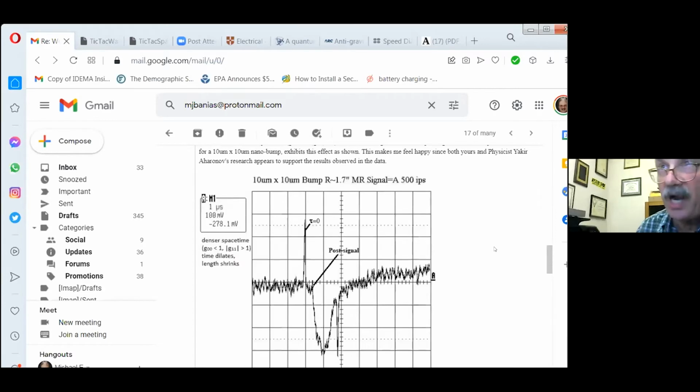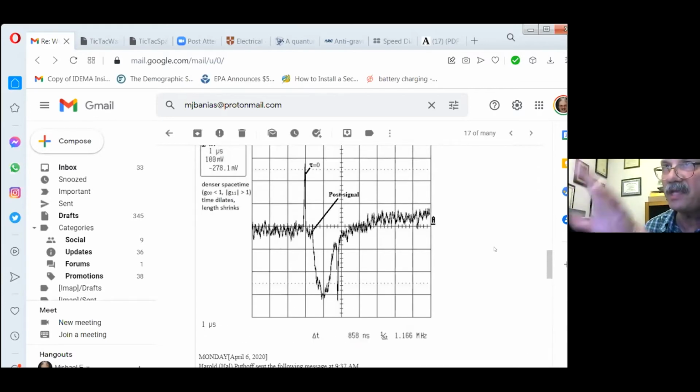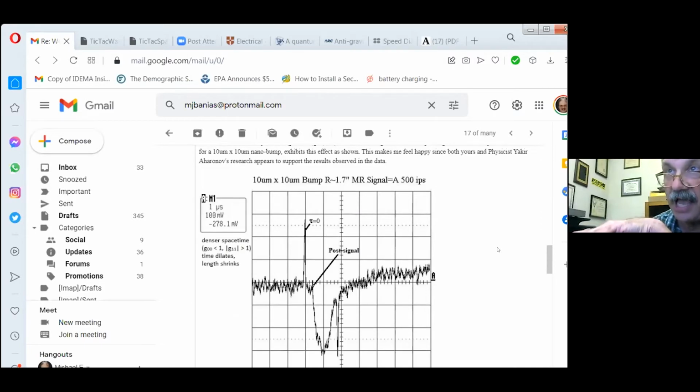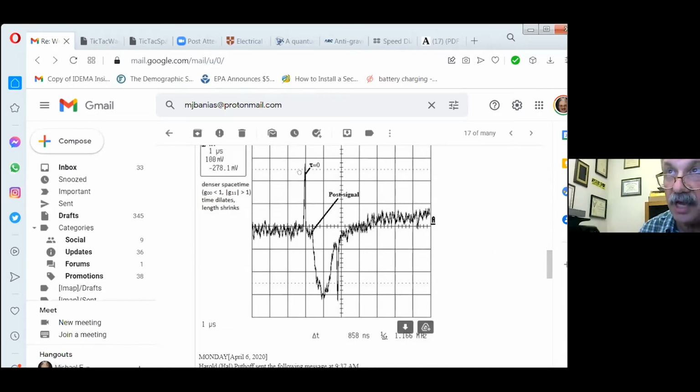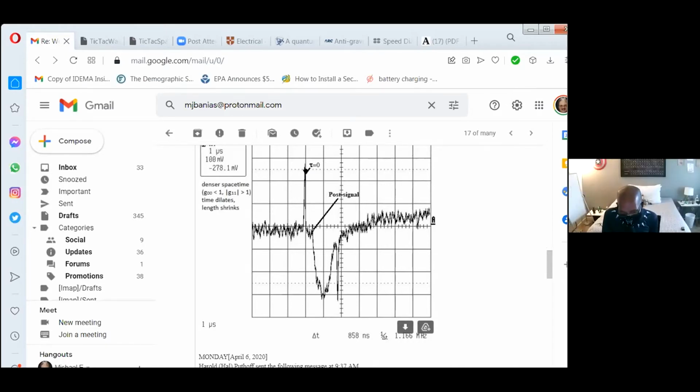I have is what I used to work on in the hard drive industry. This is a nanogravity signal from a bump on a spinning disc, and what I'm measuring it with is a thing called a GMR sensor. It's a giant magnetoresistor, part of the read head on the hard drive. Essentially, when the bump goes under it, the edge of the bump creates a magnetic induction signal. And that's what this first signal is here.